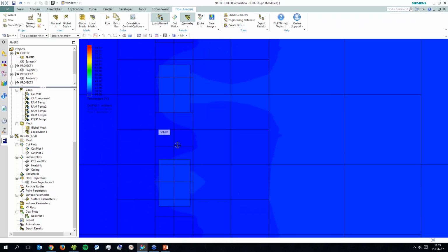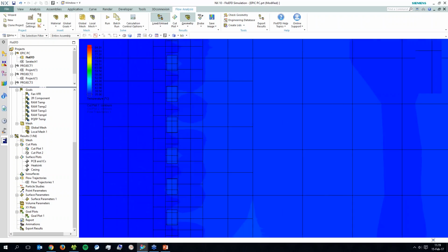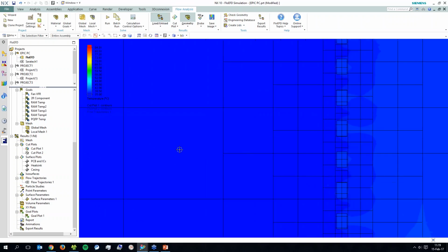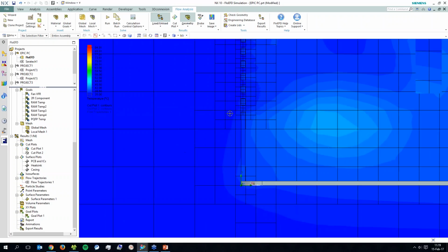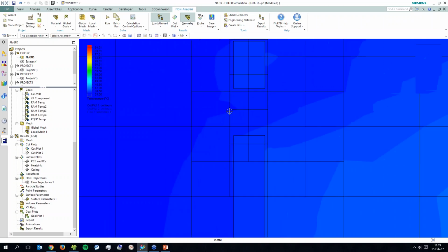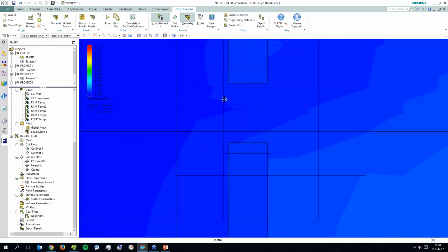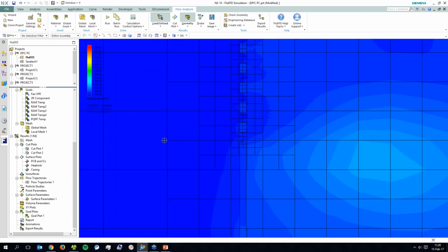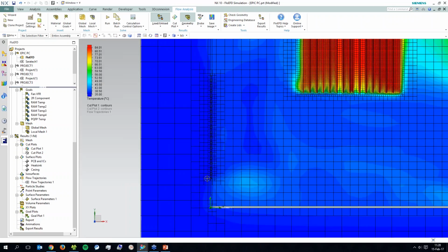So you'll see that we take a single grid cell, and we split that into 4, then 4 again, 4 again, 4 again. What that does is it maintains the aspect ratio of the cell. So the aspect ratio of this is exactly the same as the large one, and it also maintains the growth ratio. So you're going from always 2 to 1, 2 to 1, 2 to 1. So you're going to get a very robust mesh and a very robust solution from this Cartesian meshing schema.